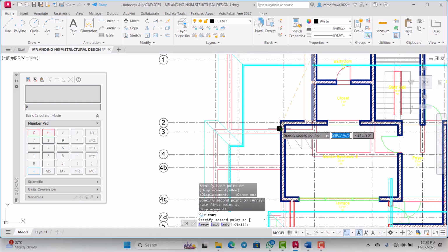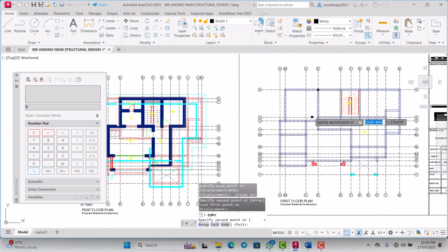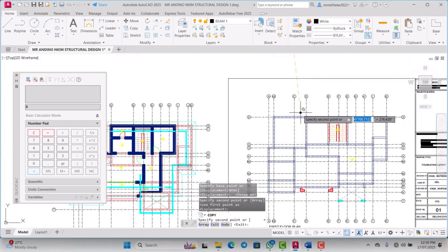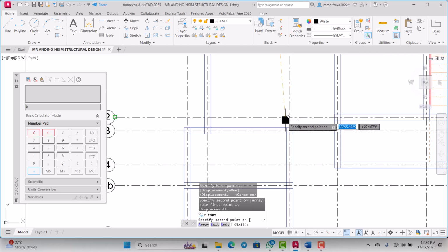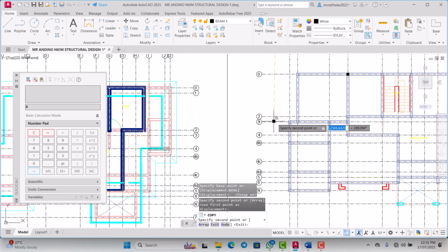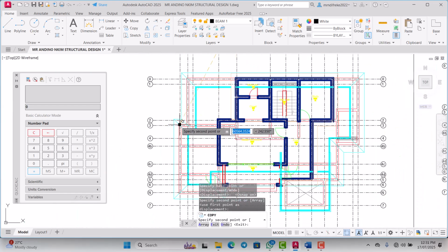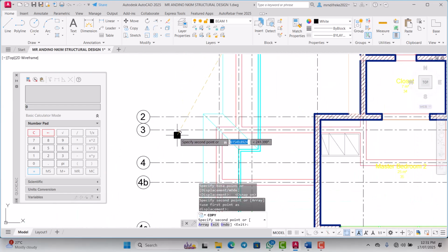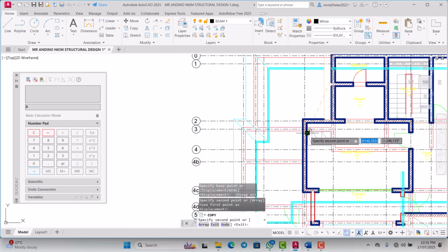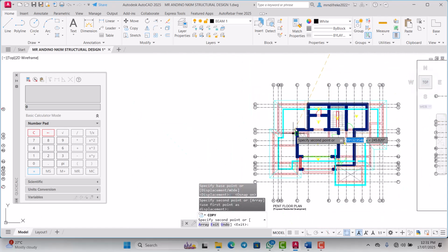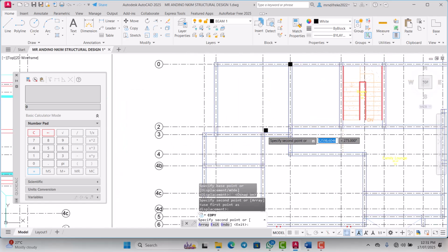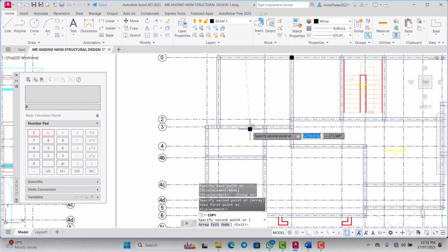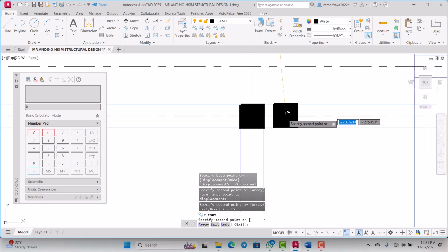2C, meaning that if I place a column at this point, this is 2C. The column here will be at the middle of the house. It will intrude into this room. So what I will do here is to shift this column. I want to shift it to where I have 3C. So I will move it to 3C. Where is my 3C? The column will be here at 3C.